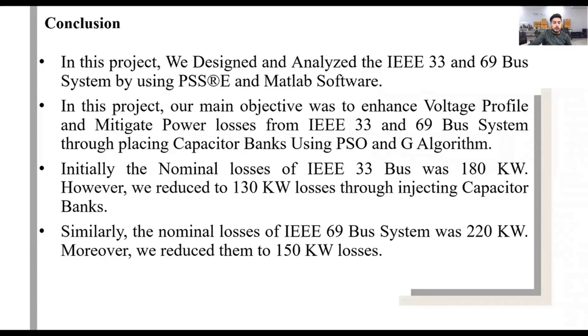So this is the conclusion of our project. In this project, we designed and analyzed the IEEE 33 and 69 bus systems by using PSSE and MATLAB software. In this project, our main objective was to enhance the voltage profile and mitigate power losses from the IEEE 33 and 69 bus systems by placing capacitor banks using PSO and GA algorithms.